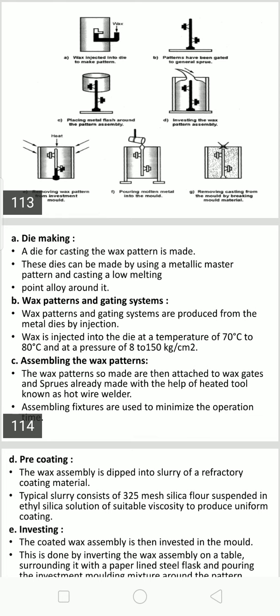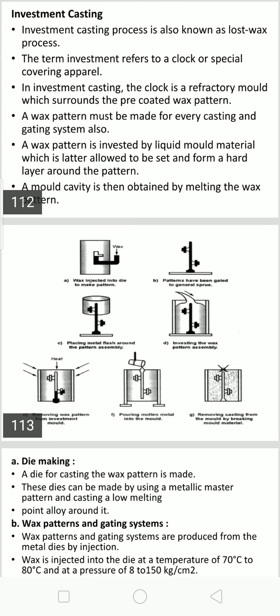This preheating ensures that the metal will not be chilled, and helps in filling molten metal in the mold cavity. Otherwise gas entrapment takes place, or the mold may be cool and become hygroscopic, absorbing moisture. That is the reason you preheat between 600 to 900 degrees centigrade in an oven.